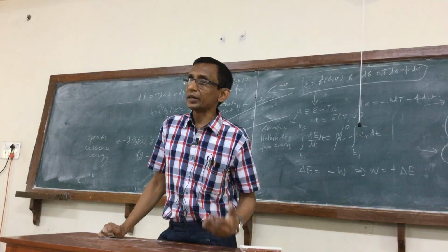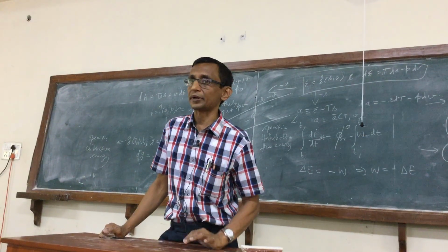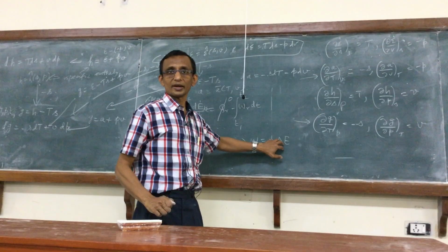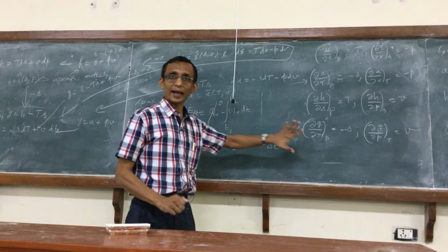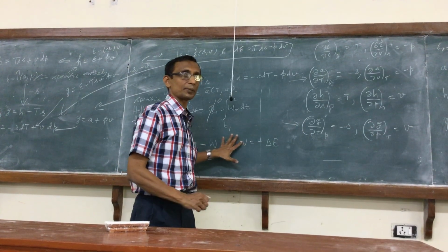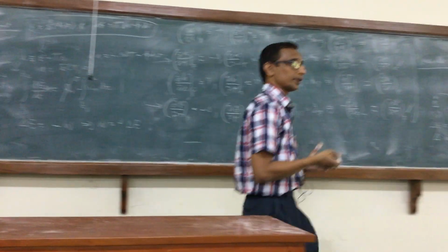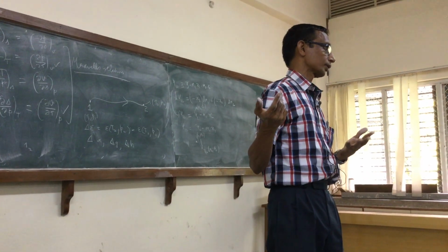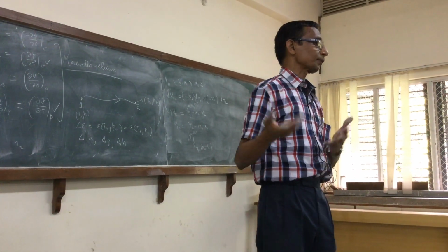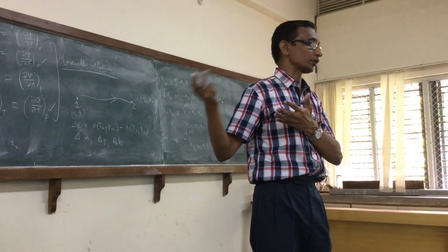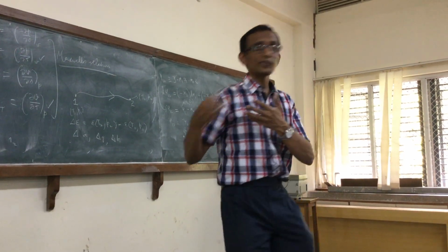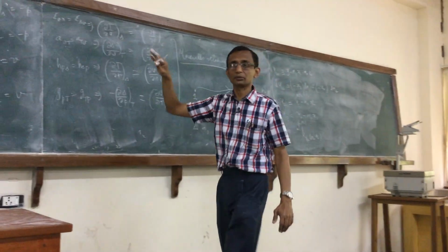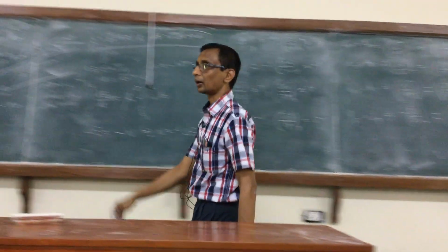This formula is valid even if the states are not equilibrium states. However, to calculate this difference, if the states happen to be equilibrium states, what this means is that I can get the work done in an adiabatic process without worrying about whether it's reversible or not, by simply calculating the change in internal energy between the two states. Now, since I have some information about the internal energy, right?